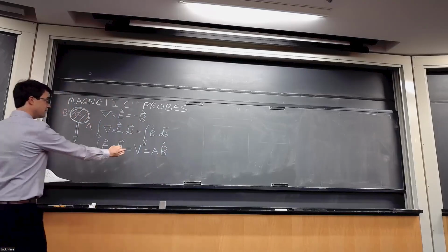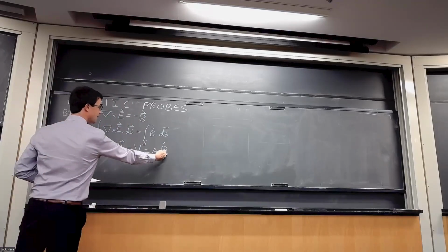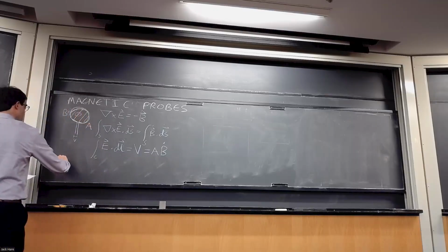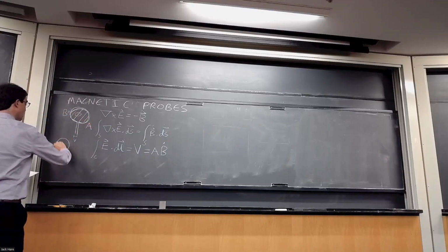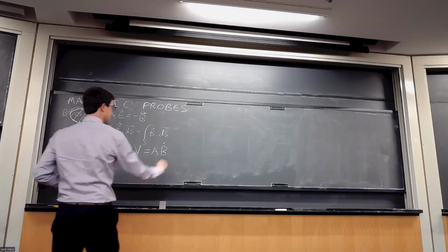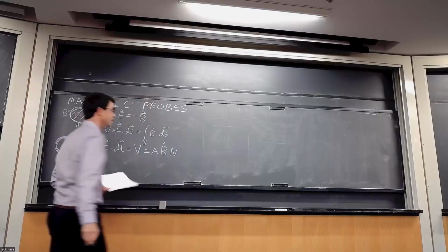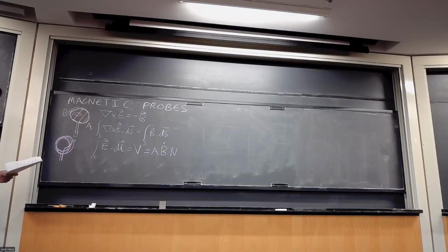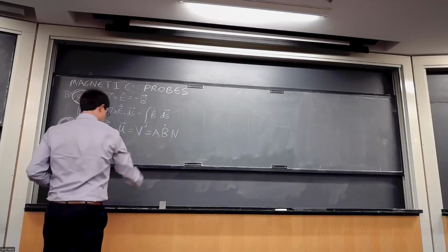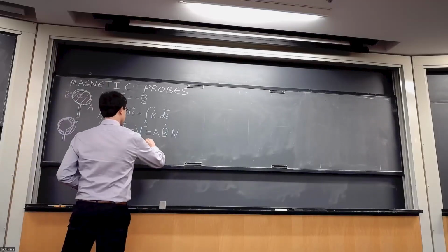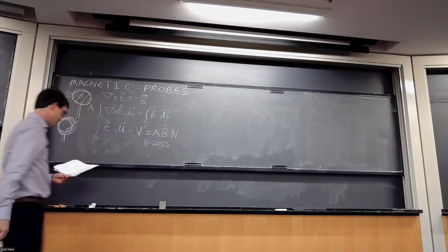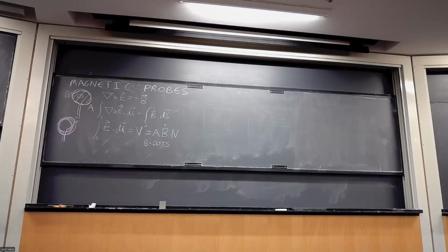And if you want to increase the voltage you get for a given time-changing magnetic field, you can put more loops on this. So your probe could have one loop, or it could have two loops, or it could have n loops like this. And we would simply multiply this by n at the end there, where n is just the number of loops we have. So that's how you make this more sensitive. And so because of this dependency on B dot here, these are called B dots. Very inventive.